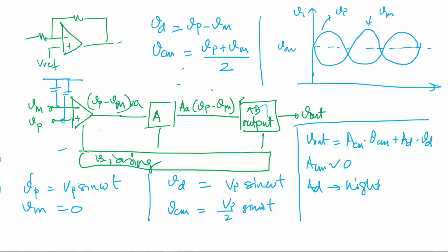So for example, you're using a phone or power amplifiers, let's say for the speaker. Typically, if you don't put music or you're not giving any sound signal to it, then the power drawn is very small. It's only when you apply music or voice or signal to it that you draw the power. And for that stage, that's not true. It is always drawing power, even if there is no signal. So this class AB stage is where you actually draw power only when there is signal. Otherwise, it just draws some quiescent current and stays there. Okay. So that's actually an output stage. A lot of times people will use it.